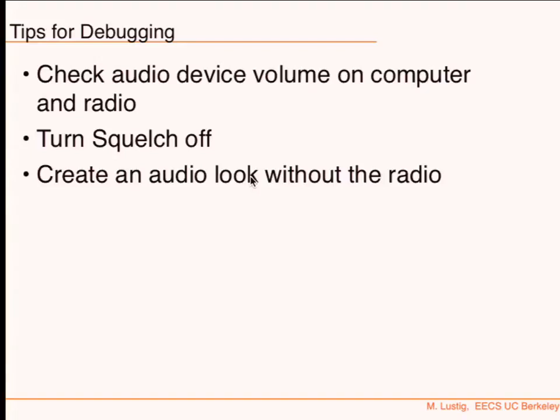Whatever you're transmitting, now we'll go to the receiver. And it's a closed loop without the radio. So that will allow you to debug a lot of things, okay? Whatever you're transmitting, you're receiving. And if you have a problem with volume, you'll be able to see it. You'll be able to hear and everything, okay? No RF interference. If it works here, then you're in good shape, okay? This is enough to pass the lab, if you can make that work. Because other RF interference is other issues. But then after